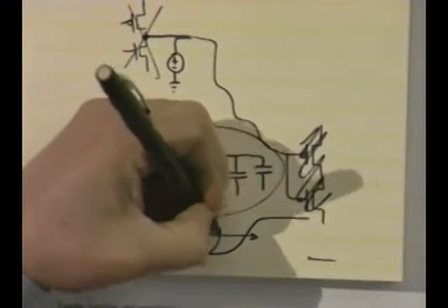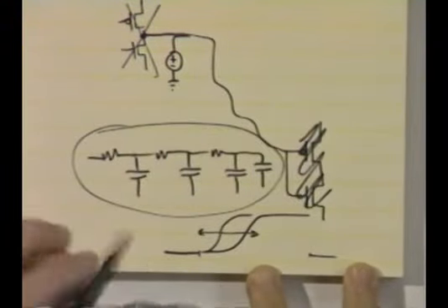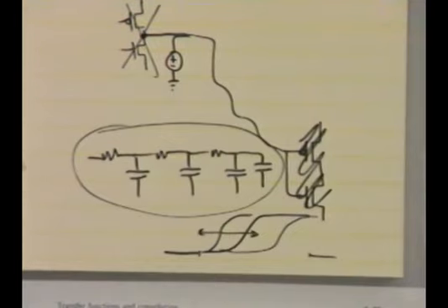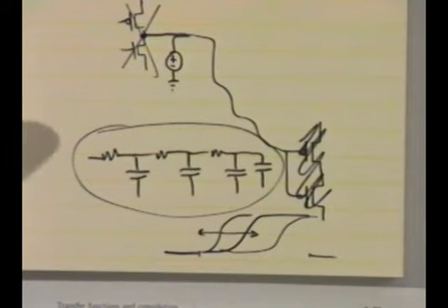This step response would look like this. If I made these wires little itty bitty tiny little things, right, then the delay might be very long. Now, of course, long delay, right, is measured in nanoseconds here, right? So what the step response of a wire in an integrated circuit does is it tells you the delay of that wire. Ultimately, that's exactly what limits how fast a digital circuit can work.